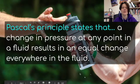Now, Pascal's principle states that a change in pressure at any point in a fluid results in an equal change everywhere else in the fluid. This is how the hydraulics work. If we squeeze that bottle, it changes the pressure and it will increase the pressure everywhere in that liquid. And so, what they do with hydraulics is they squeeze a small area and get a high pressure that then transfers to another area, and they're able to use that pressure change to use that force to move something like a large bucket on machinery.